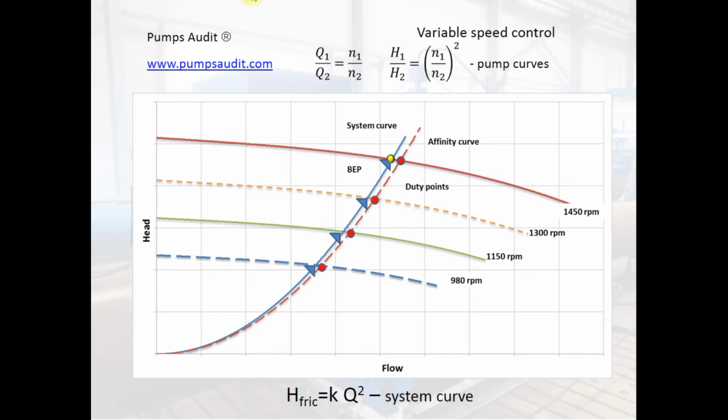These two curves always coincide, and if the pump was selected so that the operating point lies close to the best efficiency point, for other speeds operating points will also lie close to the best efficiency point. So the speed control is the best method of pump control in systems with mainly friction losses.